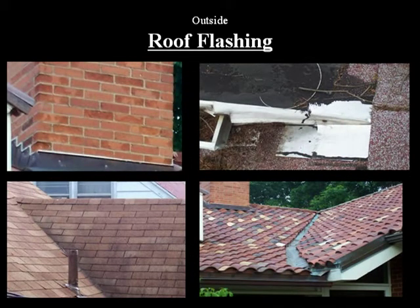One of the main causes of leaky roofs is failure of the flashing. Flashing is needed around chimneys, plumbing vents, valleys, and where a lower level roof intersects with a higher wall. Flashing fails for two basic reasons. It corrodes with age, or wind and ice has caused it to come loose. It is hard to see problems from the outside, so check under flashing areas during the attic inspection.